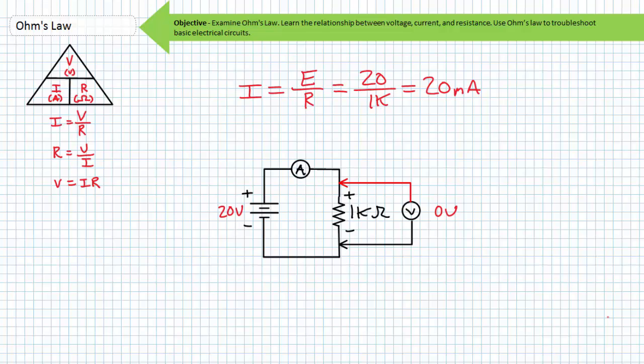If there is no voltage drop across a resistor, it means that there is no current through it. Ohm's law says so, and your ammeter would indicate so. Ordinarily, a 20 volt source would supply a 1 kilo ohm resistor with 20 milliamperes of current. If there's no current, 1K times 0 yields 0 volts. Did you turn the source on? You'd be surprised how many troubleshooting scenarios are resolved simply by pressing the large red switch that says on. I've done this myself more often than I'd like to admit.